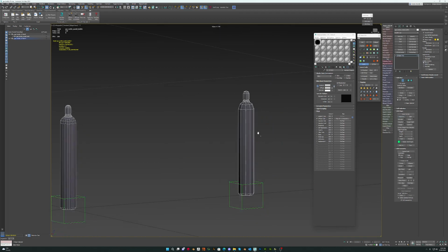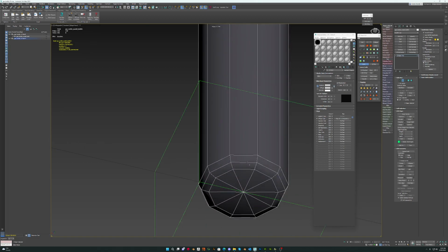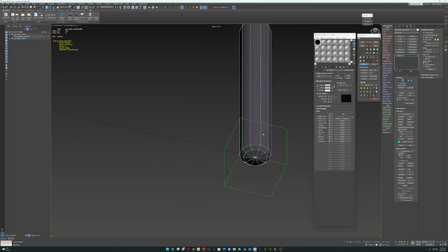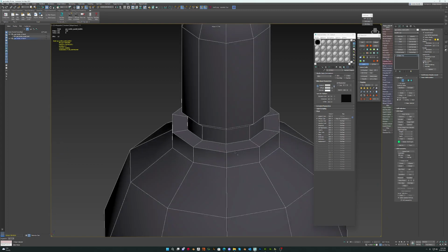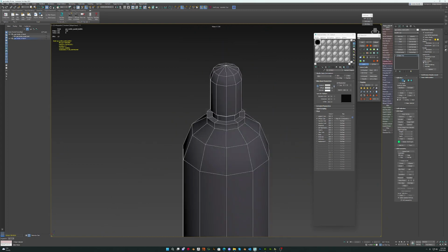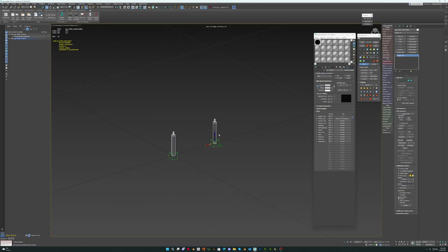But be aware of the silhouette. The silhouette shouldn't really change that much because you will notice it. For further away LODs, it doesn't matter that much, but they will be checked by ED. Okay, so LOD textures. We've discussed LOD 0 and the way the V-Ray House 5.1 material is applied, which is what we've created here. For LOD textures, there is only an MR map and a diffuse map. There are no other maps.